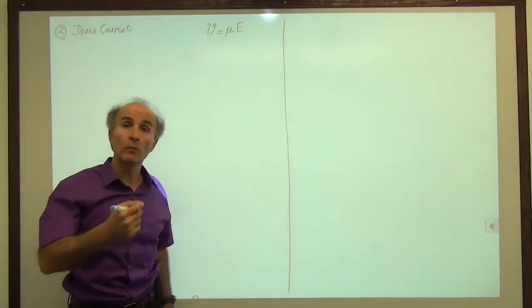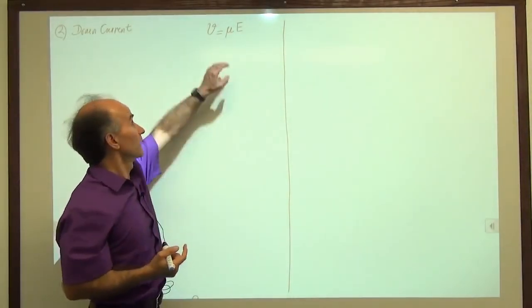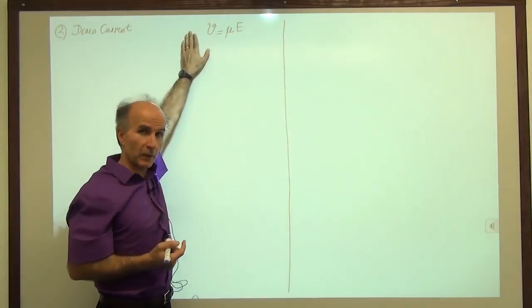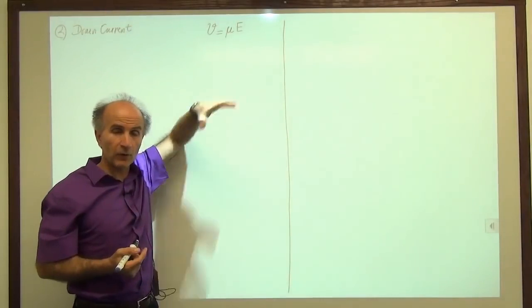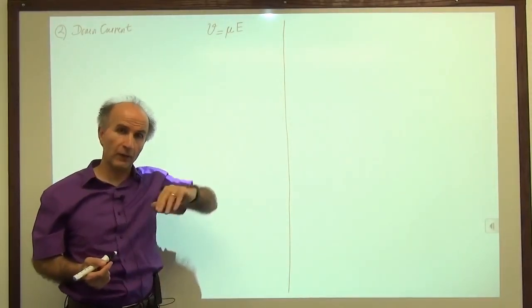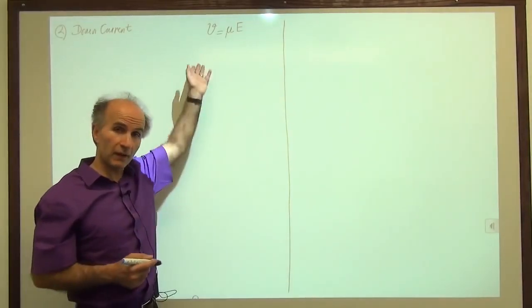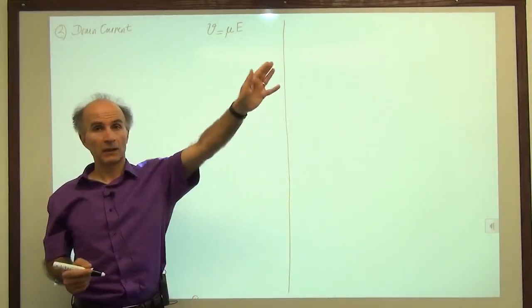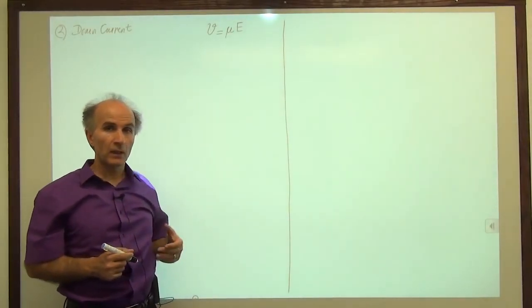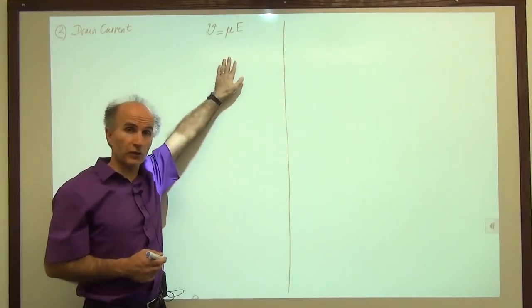Mobility indicates how mobile the charge carriers are. We saw that, for example, mobility is higher for electrons than for holes. And the velocity that we obtain is like this. As I mentioned before, this is like a terminal velocity when a parachuter falls with the parachute open. So the electrons eventually reach this velocity, and at this velocity they flow through the semiconductor. So we should be able to calculate the velocity of carriers, or at least we have this equation for them.